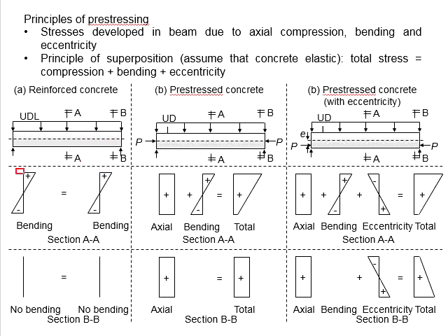Now we look at the stress at the midspan. The UDL will cause bending to the beam. This bending response will cause tensile stress at the bottom of the beam and compressive stress on top of the beam. In terms of the stress, we will take negative to represent tensile and positive to represent compression.